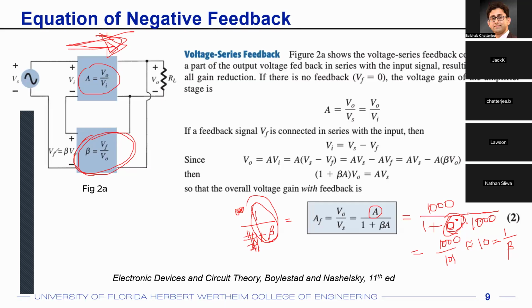But when you're buying the op-amp, everyone had bought op-amps for your lab classes, right? You'll see, like in your lab, that everyone's op-amp will behave differently because they can come from different batches. But if you're buying, let's say, 10 resistors at the same time, and they are provided to you by the manufacturer directly, those manufacturing variations will be in the same directions. What that means is that the ratio of the resistors will be the same. So if your 1 kilo ohm has become 1.1 kilo ohm, and if your 1 ohm has become 1.1 ohm, the ratio of those two is still 1000. So it's easier to create a beta network that is more stable.